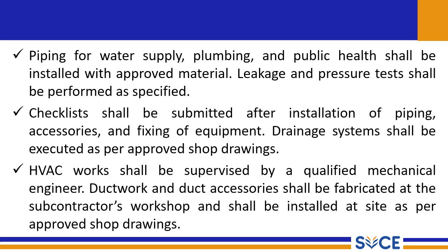Piping for water supply, pumping, and public health shall be installed with approved material. Leakage and pressure tests shall be performed as specified. Check tests shall be submitted after installation of piping, accessories, and fixing of equipment. Drainage systems shall be executed as per the approved shop drawings.